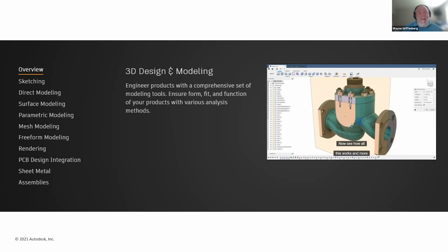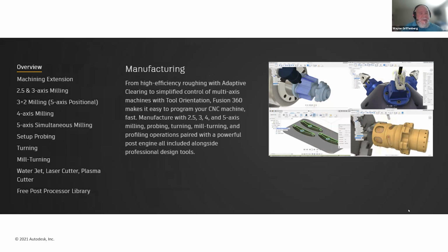If you're working with assemblies, to bring in vises and make fixed jaws or even soft jaws for those different vises, you want to have a powerful CAD interface to be able to work with. Same thing if you're working in the CAM workflow, you want to focus on a tool that's going to have very robust capabilities and toolpaths for 2.5 axis and 3-axis milling. If you do positional, 3+1, 3+2. If you're doing multi-axis simultaneous, you have to take these things into consideration and think about the tool that you're going to use for that integration of CAD and CAM.